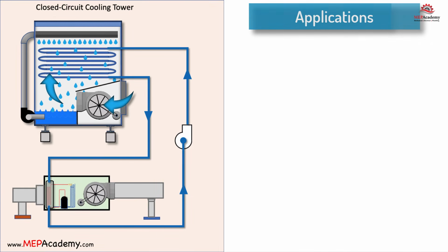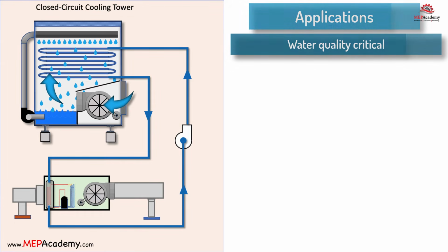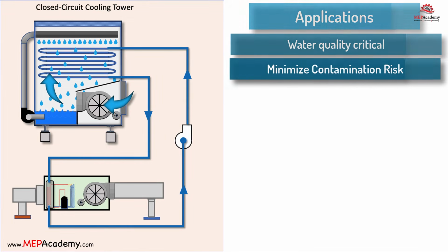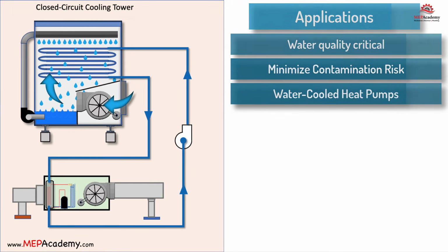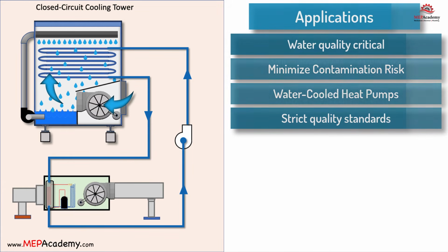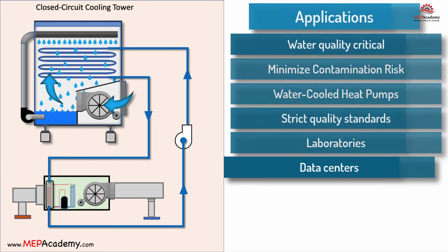Applications. Closed-circuit cooling towers are often preferred in applications where water quality is critical and there's a need to minimize the risk of contamination. This makes them suitable for water-cooled heat pump applications in those industries with strict quality standards such as laboratories and data centers.